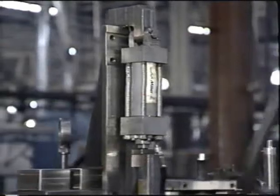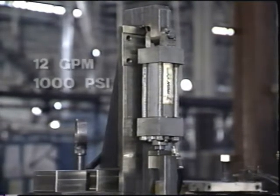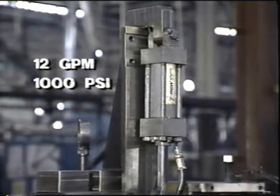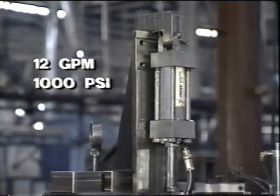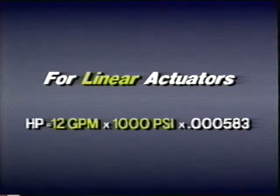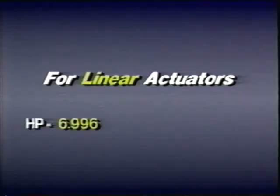0.000583. As an example, suppose a cylinder takes 12 gallons per minute at a pressure of 1,000 pounds per square inch. What horsepower will it develop? To find the horsepower, simply multiply 12 times 1,000 times 0.000583. The answer is 6.996, or about 7 horsepower.